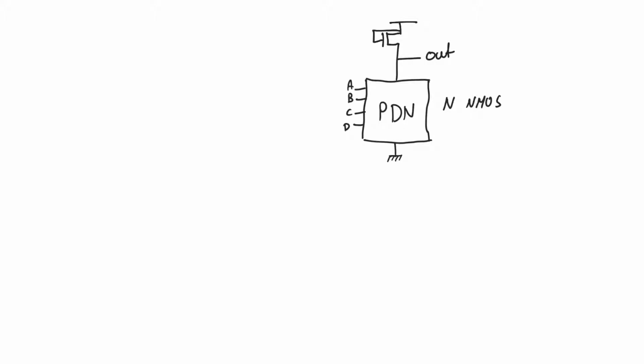There will be a network. This network will be called the pull-down network, and in short, PDN. The pull-down network will be responsible for connecting the output node to ground conditional on a number of inputs. The PDN will consist of n NMOS transistors. Each and every one of the NMOS transistors will accept a logic input. So there will be a number n of logic inputs going into this pull-down network. There will also be a single diode connected load ML at the top.